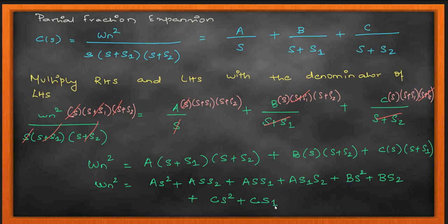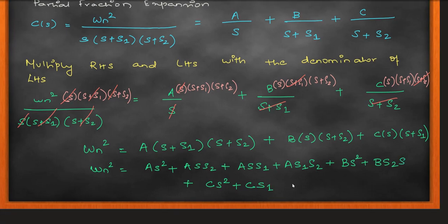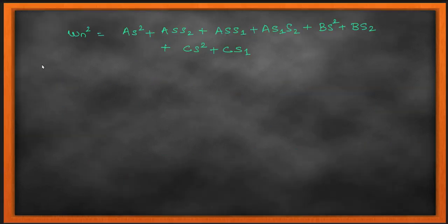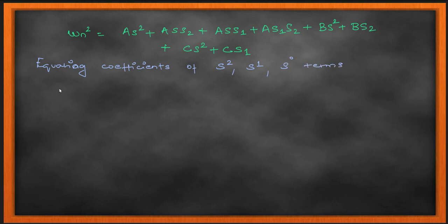So you want to work with the whole quadrant. You want to work with all the 4 quadrants. You want much more room for your roots to occupy, so that your systems can have more flexibility in your designs. So that is why we are not very particular about this overdamped system when it comes to usage in our designs. We mostly use the overdamped system to see what happens if for some reason your zeta becomes greater than 1. So you need to have an analysis for that.